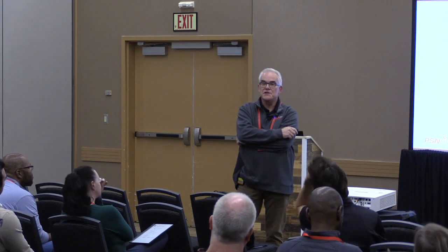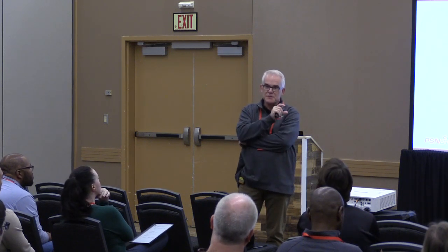At this point, I think I have a few minutes left to take some questions. Okay, sir. You mentioned oxygen seems pretty easy and obvious for radiant tubes to monitor each individual burner. For a direct fired furnace, what do you do for monitoring each individual burner? So there we're actually looking at the ratios of air to gas. So we're monitoring how much gas and how much air. You're looking at valve position, or at orifice meters?